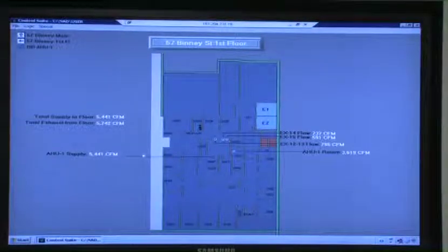You know how much CFM is coming from AHU1, right? AHU BB1 supply, out of this ductwork supplying this area, this floor, is 5,397 CFM. We're returning 3,620 CFM into the return right over here, and we're exhausting three locations of ductwork that branch out on the floor. This is just the shafts that we know are going to this floor. 735, 5 something. Those are the fans, okay? Then we have totals here. Total supply to the floor is this. Total exhaust from the floor is this.